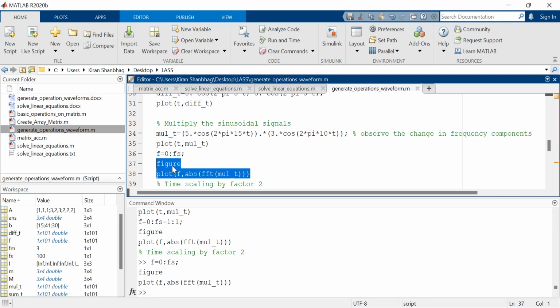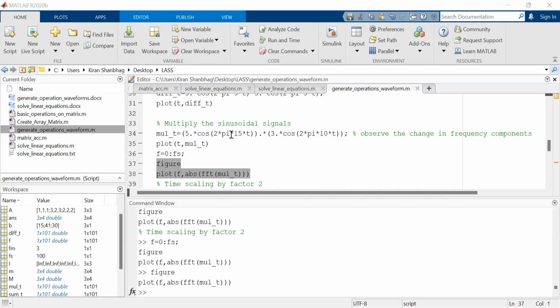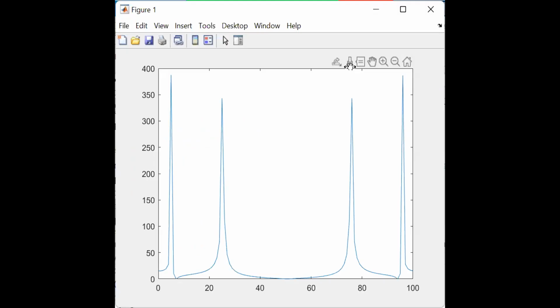What did I say? Cos A cos B equal to half of cos(A plus B) plus cos(A minus B). So here we are. This is the Fourier transform. The frequencies were 10 and 15. The sum gives you 25. As you can see here, there's a frequency 25, because the x-axis is frequency. There is an impulse at 25. And there is A minus B, 15 minus 10, that's 5. So two new frequencies have popped up. That's what multiplication does.